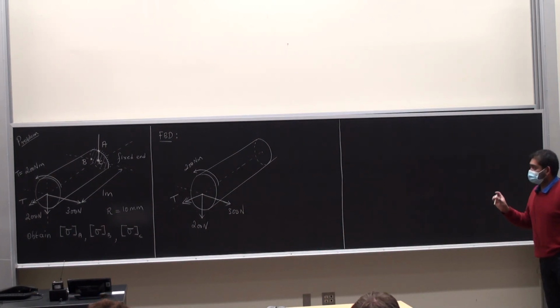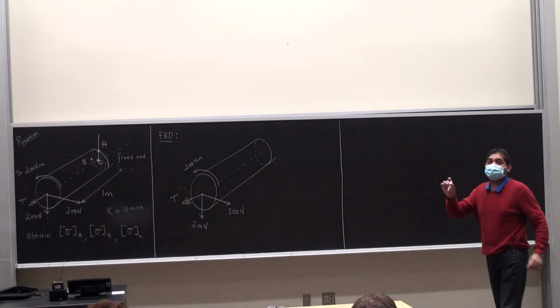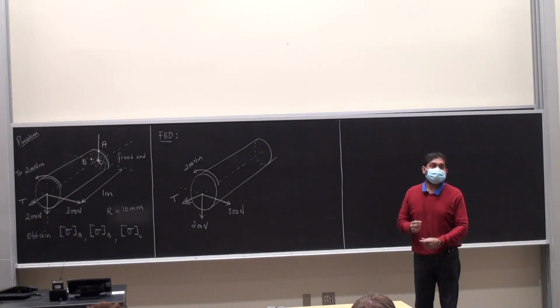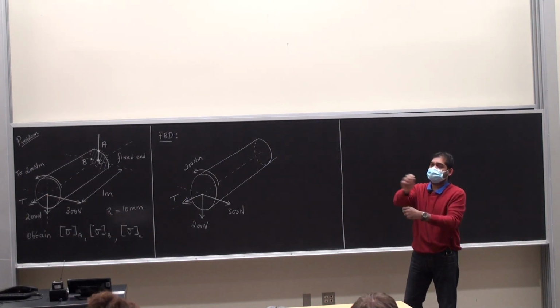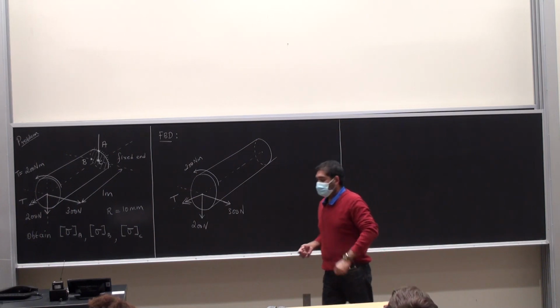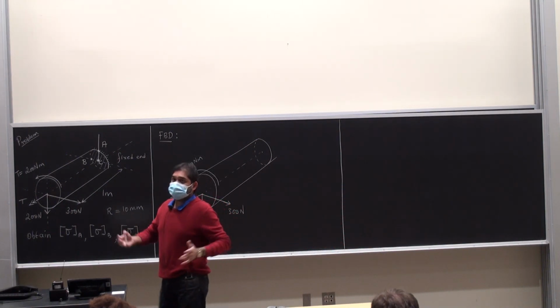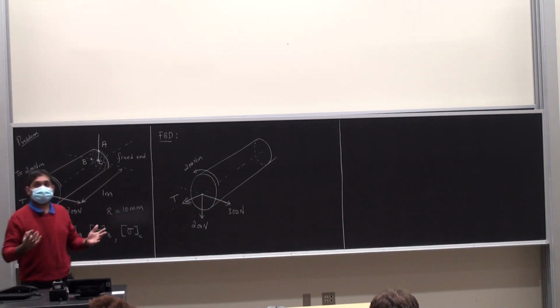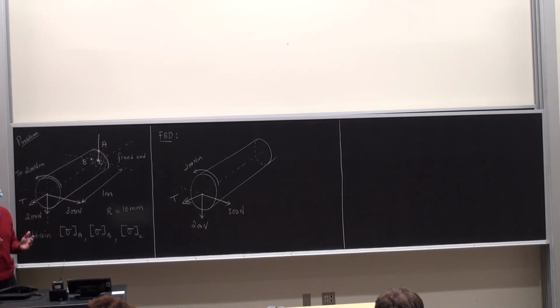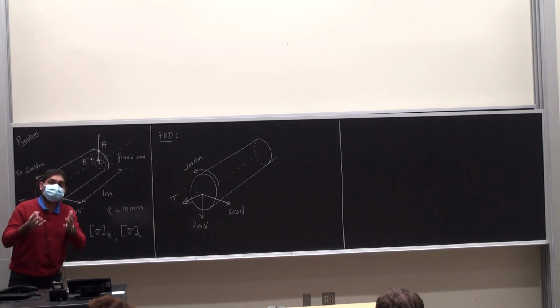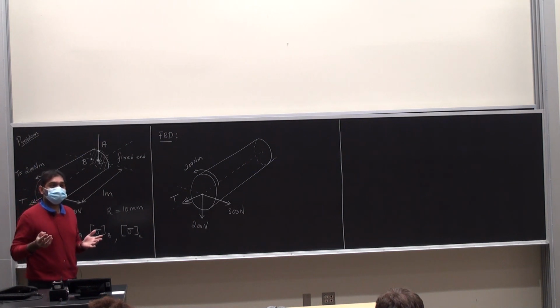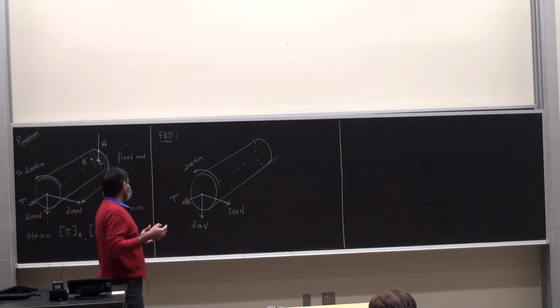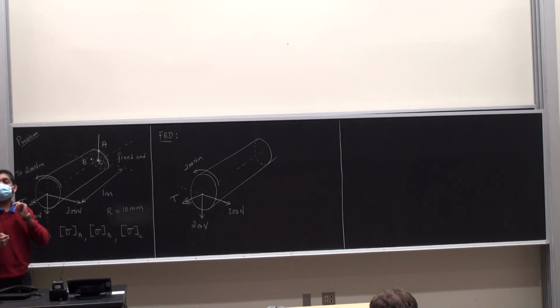before I start marking the support reactions and so on, I set up a coordinate frame at the fixed end of the shaft. So here is where you have freedom to be creative. You can call the vertical axis the z-axis, the horizontal axis the y and the x-axis. That's completely up to you. In some problems, you may have a coordinate frame given to you, which makes your job easier. In this problem, there is nothing given to me, so I'm going to choose my own frame.